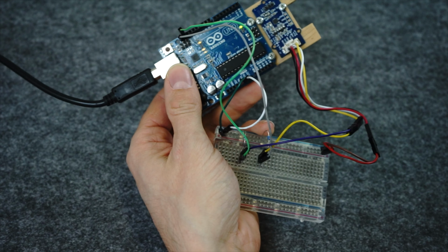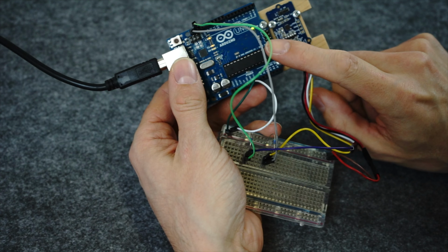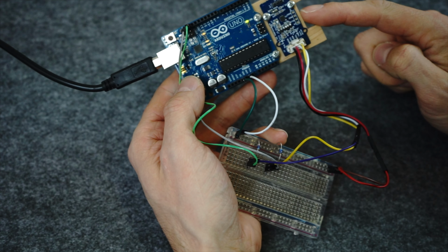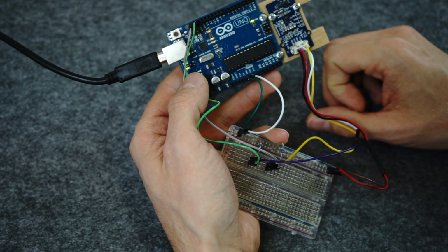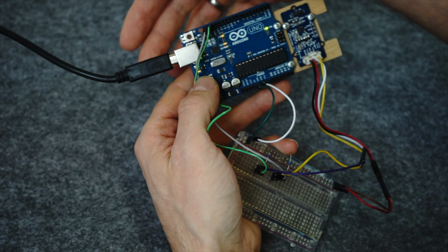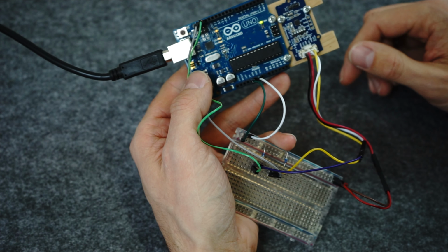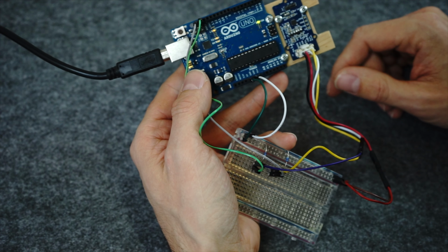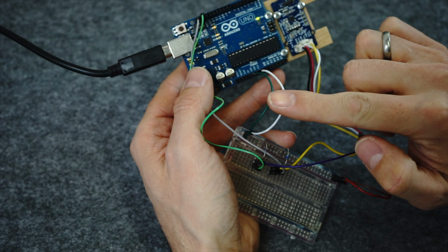In this video, we will take a closer look at the following setup. An ATmega328P connected to one inertial measurement unit. In particular, we use an MPU9250. The ATmega, which is the microcontroller on this Arduino Uno board here, is connected to a computer, which also powers the complete setup via USB. The IMU is powered by the 5-volt supply of the Arduino, internally just wired to the USB power supply. And we then of course connect all modules to a common ground.